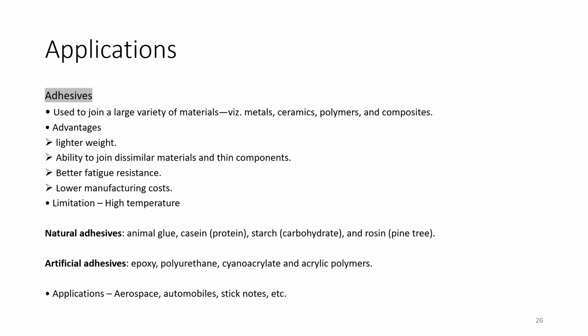Adhesives are used to join a large variety of materials such as ceramics, polymers, and composites. Their advantages include lighter weight, ability to join dissimilar materials and thin components, better fatigue resistance, and low manufacturing costs. Limitations include that they can't be used at high temperatures. Some of the adhesive examples are given and applications as well.